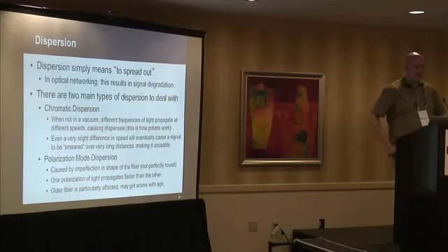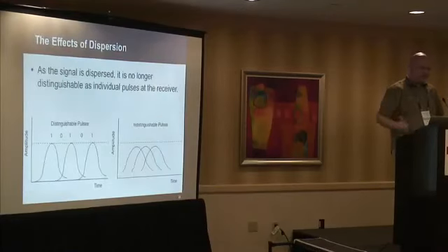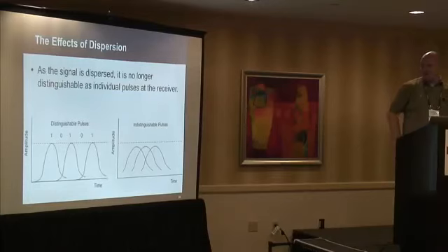And the other one that's less of a deal, but still out there, is called polarization mode dispersion. And that's caused by the fiber not being perfectly cylindrical, imperfections in the fiber, just moving it around. If you know polarization of light, sunglasses where you turn it one way or the other and you're seeing half the signal, you're going to have one type of polarization traveling faster than another if the fiber is not perfectly shaped. And what this causes is you get a smeared out signal, and now you're sitting on the receiver side, you can't actually figure out what it is.